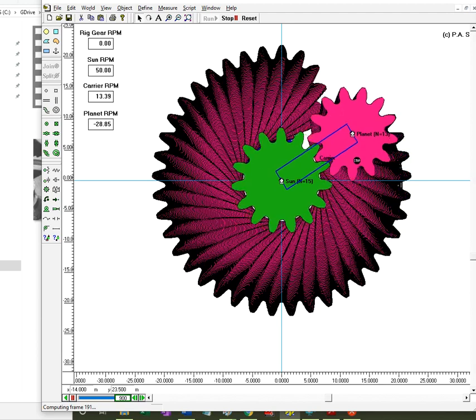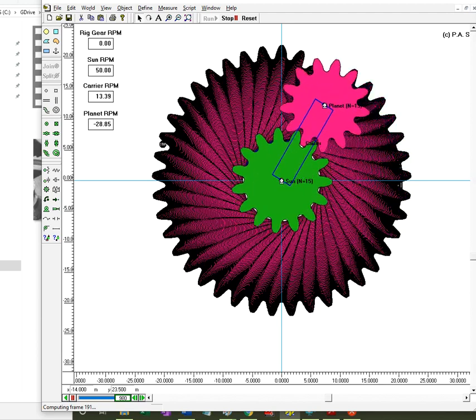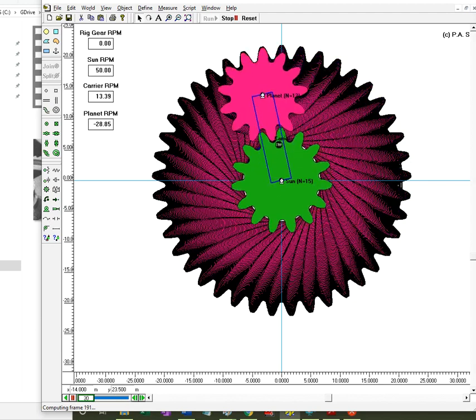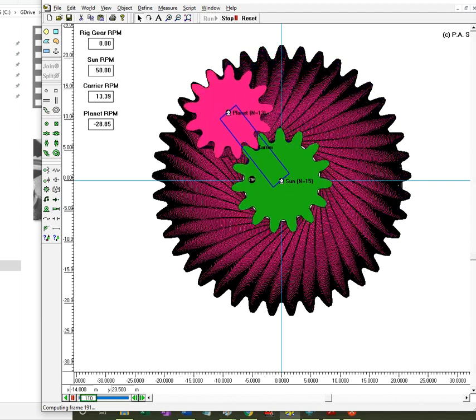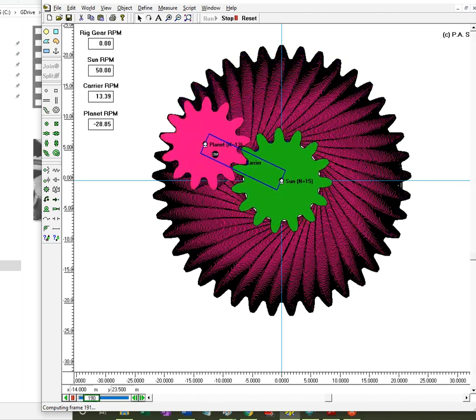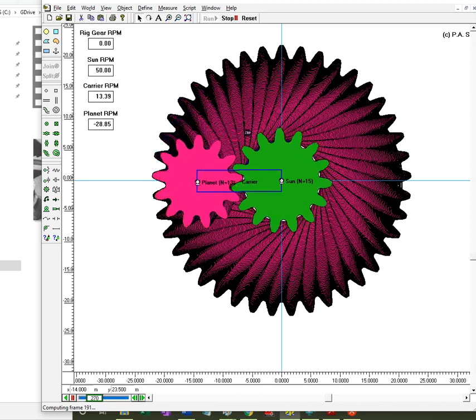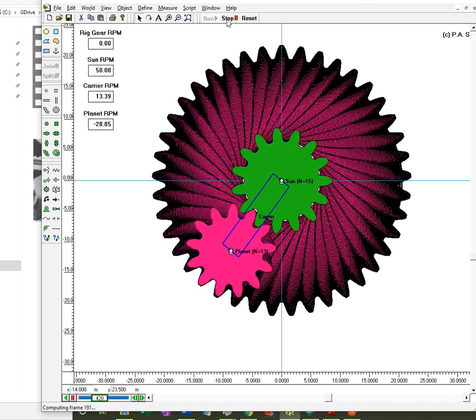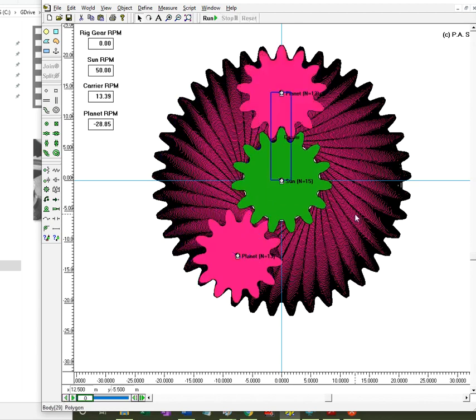The correlation between the blank geometry and what happens inside of the machine should be based on the number of teeth of both the tool and the future gear. When discussing envelope gears, we'll look at a dedicated application where you can even change the number of teeth.